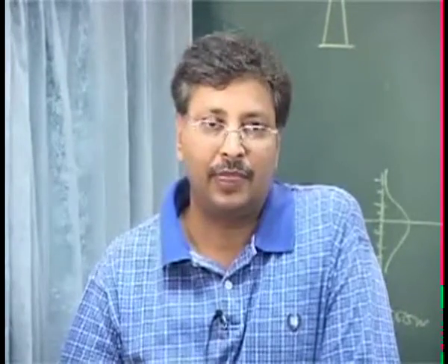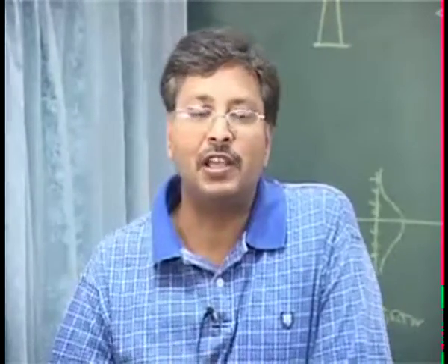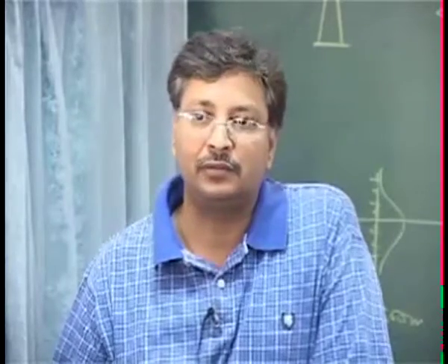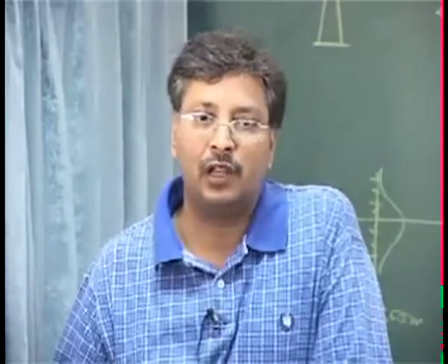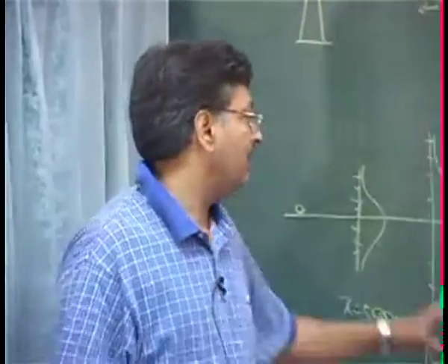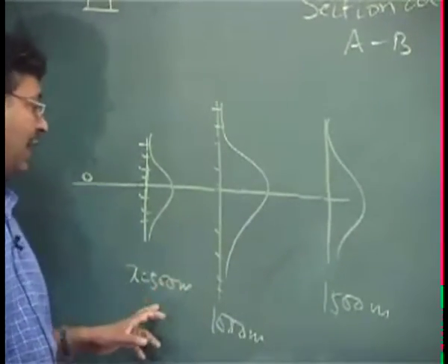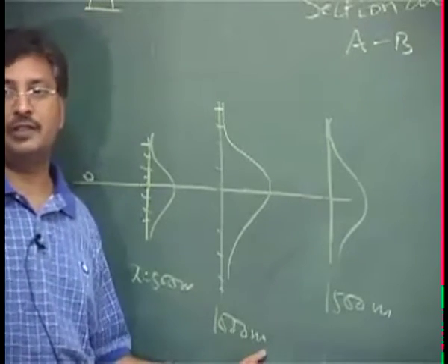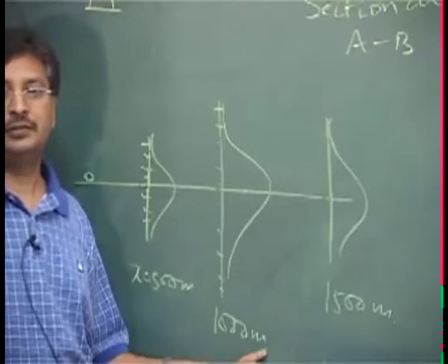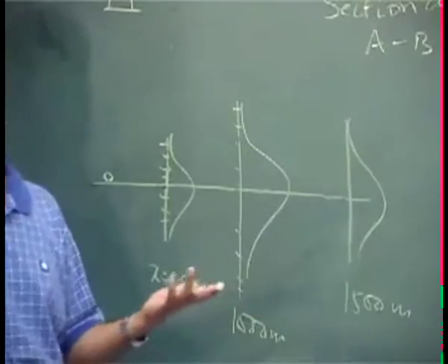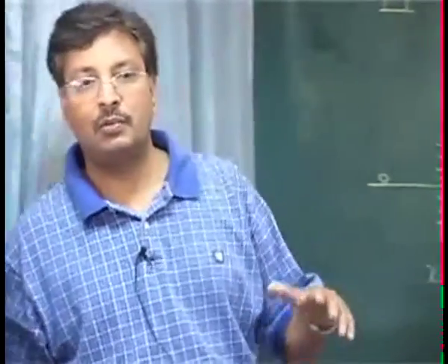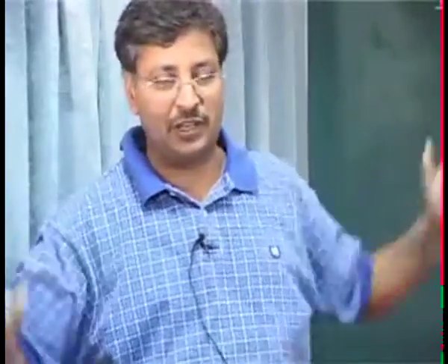And what else will sigma y and sigma z depend on, other than the x that we are seeing? Tell me, with x, will sigma y increase or decrease? Increase. So that is one thing that is clear. Because the plume is expanding, sigma y is increasing.